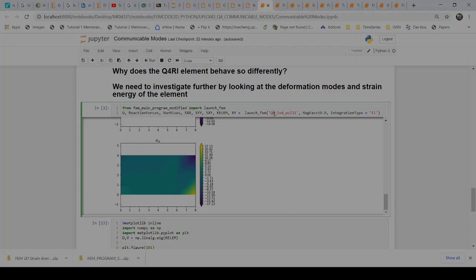We saw what happens with large angular rotations: there's lots of strain because of the linearization we've done. But first, this is just a sanity check before we start looking at the representation. So I expect to see 3 zero eigenvalues, and the modes associated with those 3 zero eigenvalues should look like rigid body motions.